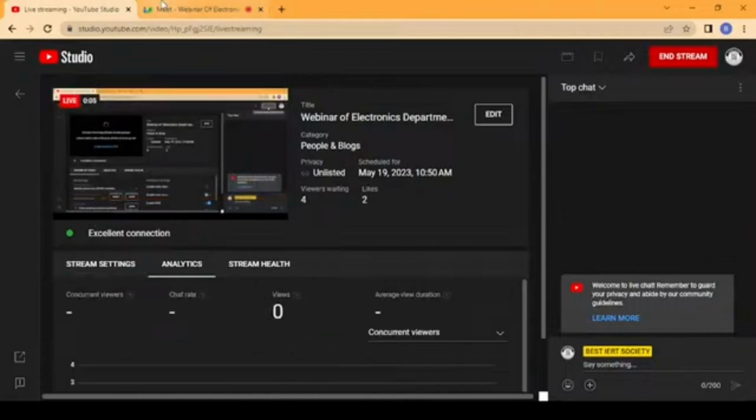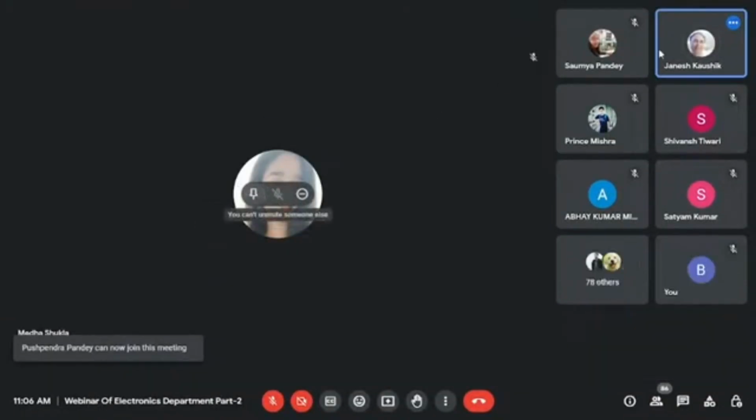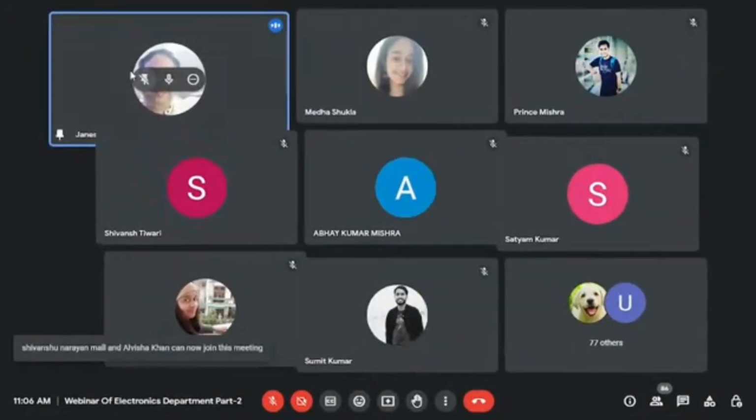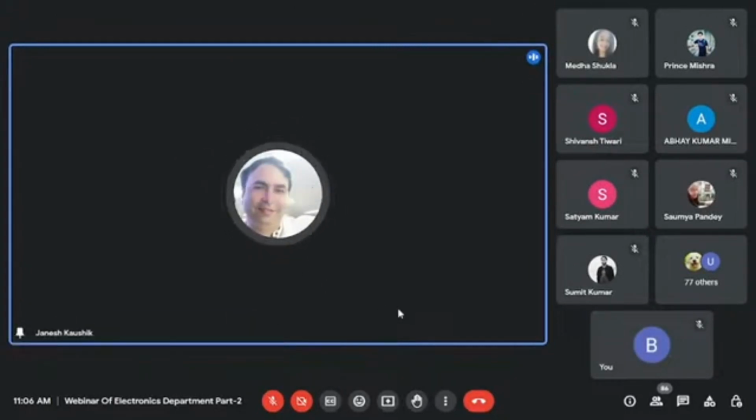Last meeting we covered the semiconductor basics and p-n junction devices. In this talk, I will try to elaborate and build the theory based upon the earlier topics presented, and I will introduce one more topic, that is the metal semiconductor junction diode. That is the Schottky diode, as we call it, because Schottky gave the theory of the barrier lowering effect due to the metal and the electron present in front of the metal in the semiconductor. Basically, image charge barrier lowering.